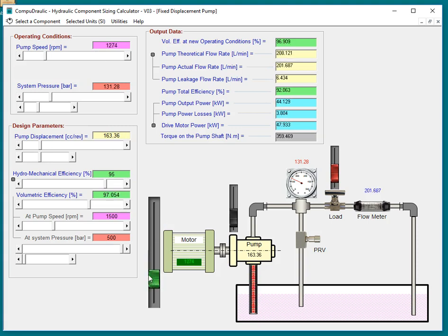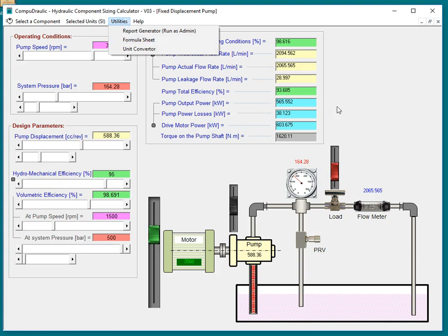So you can change here the speed, you can change here the pump size, you can change here the pressure in front of the pump. So that gives you a better sense, but it won't change any of these results. When you're done with your calculation, what you should be able to do also is to go here, rather than take a screenshot, to save these data.